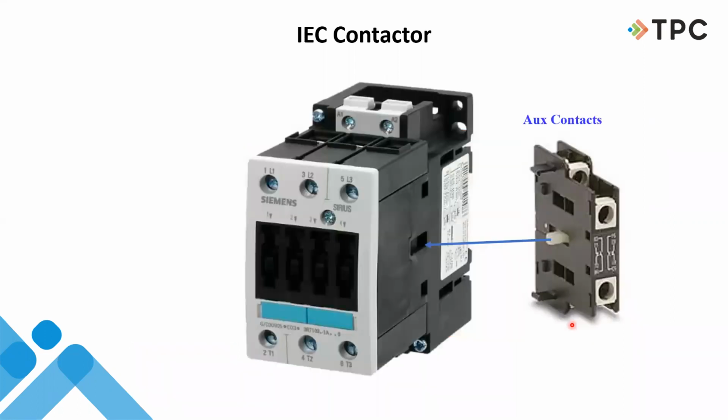Okay, so here's a contactor, and on this one Siemens has put both sets of numbers. So I have 1 and L1, 3 and L2, and 5 and L3. We talked about the odds being up here and the load being down here. Now I have places for auxiliaries that can snap right in, and that way I can have power contacts and auxiliary contacts on the same device.